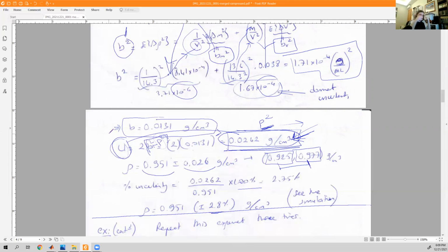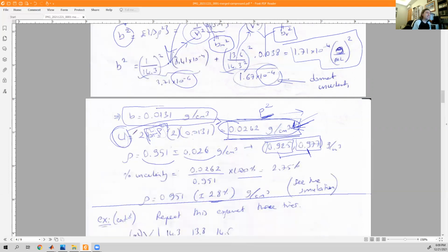Note that the simulation was the kind of exact solution, using some simplifications of the modeling approach. But the method that I applied here, using partial derivatives, was using the first term of the Taylor series. So it was a linearization. As you can see, that linearization and this method work pretty much fine. It's not the exact simulation result, but it is very close.